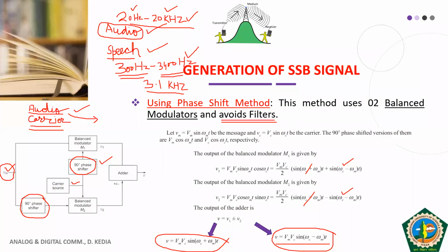So when we talk about 90-degree phase shift, it means we do not have a single frequency to phase shift. We have so many frequencies for which we need to phase shift for modulating signal, whereas for the carrier, we have only one frequency to phase shift. Shifting the phase of so many frequencies at a single value of the phase shift, say 90 degree, is not that easy.